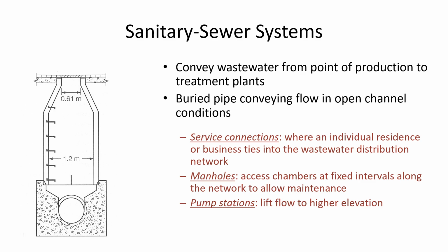And one of the impacts of that is that the water flows at a low velocity through the pipe and things settle to the bottom, especially at the nighttime hours when there's a really low flow rate. Then sediment and debris that inevitably ends up in sewers sometimes can settle to the bottom of the pipe and just become stationary. And so hopefully what we'll see is that during a high flow period of the day, or maybe during a storm event, a big surge of water comes through the pipe at a higher velocity and scours any of that settled debris.